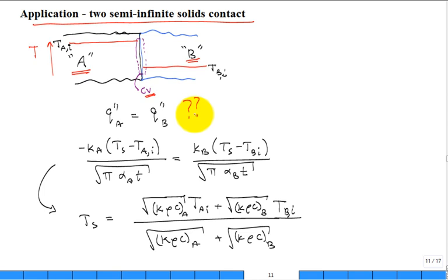So what comes out of A goes into B. The way we've drawn it, A is warmer. What is our equation for the heat flux coming out of A? Well, it depends on that surface temperature. We had A will jump to a surface temperature. The surface temperature could be close to the value of the temperature of A initial. Or the surface temperature could be down here, closer to the B initial.